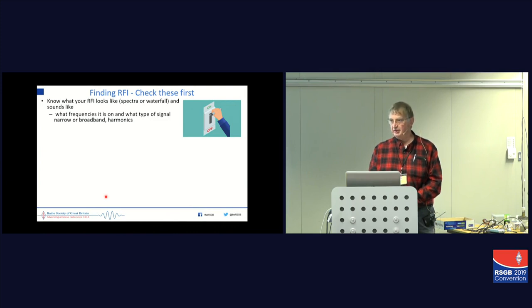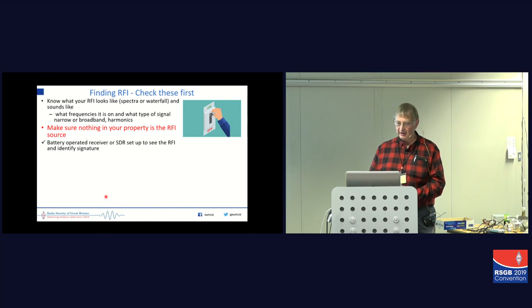And this is where it becomes important to know what you're looking for, because I can guarantee that with every breaker in that house you turn on, your noise level is going to ramp up. So if you don't know exactly what you're looking for, you'll probably find a noise source. Maybe a great idea to fix it, but it isn't what you started out trying to fix. So make sure nothing in your property is the source. To do this, you have to have a battery operated receiver or an SDR running on batteries, as that is.